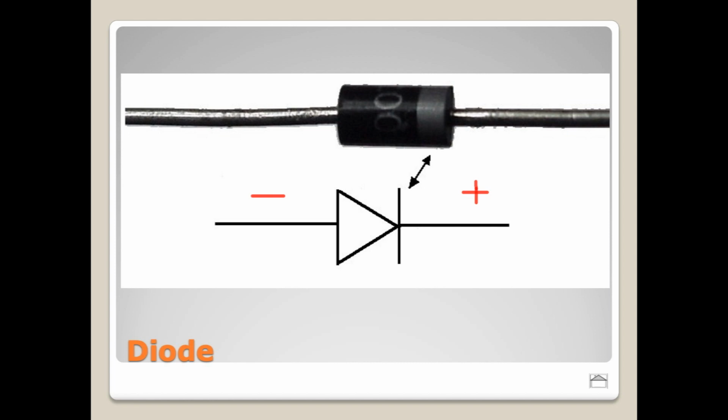In other cases, you might just lose functionality in a particular part of a piece of equipment, but it is important, right? Now, on an actual schematic, you will see the line, you'll see the arrow, so you can kind of understand that. When you're actually working with a circuit board, usually this shape along with a stripe on this end will actually be drawn, or what we call silk screened, onto the board, and you can use that as a guideline for being able to figure out which direction it goes.